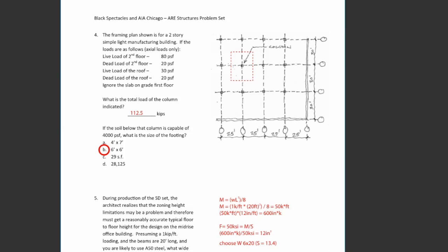The reason I would say that is that anybody who's actually done concrete work knows that if you start giving people an answer like the footing should be 5'2 and 5/8 inches, they don't build to that. It's just not how concrete works. Generally you're going to round up, maybe to a 6-inch line, or maybe a foot line. If you're being a little more tight and controlled, maybe every 2 inches or something, but a 6-inch increment would be fairly typical.